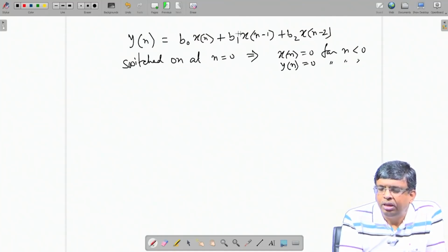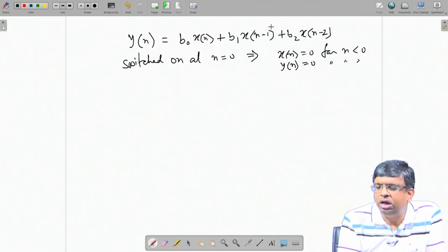Next time, again same job, a multiplication with the built-in constant, multiplication of a data, and then add with a data. Earlier it was 0, now it is data, and then whatever is generated, now you come here again, a built-in constant times a data plus whatever is generated. So, multiplication and then multiplication output plus something already generated. Okay. So, multiplier and accumulator, multiplication and accumulation, MAC.